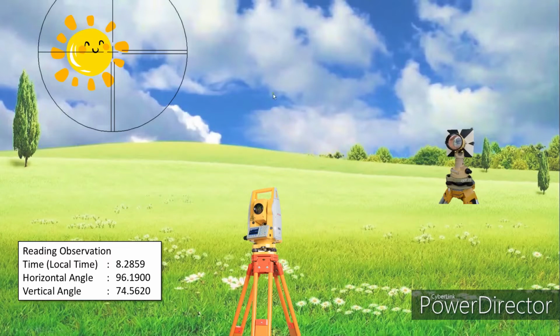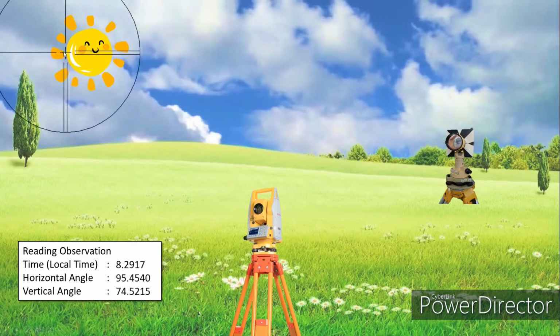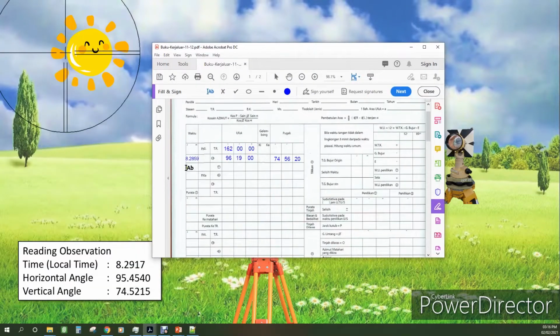Next, we move the total station target to the left hand side of the sun. We get a reading here and record it in the booking at 29:17. This is the time of the observation, this is the horizontal angle, and the last one is the vertical angle.